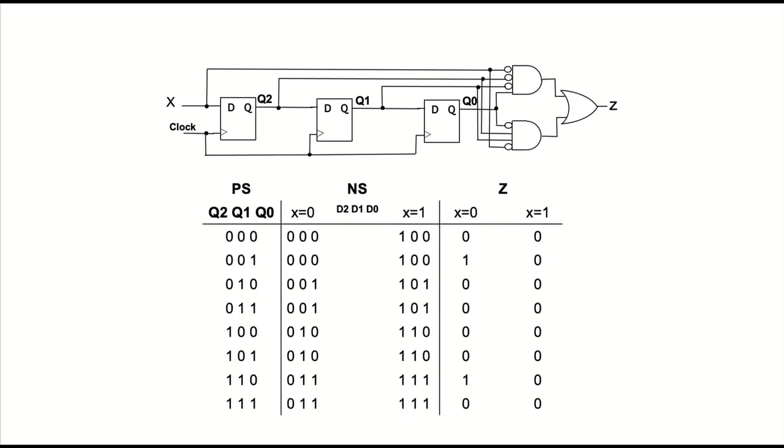We could draw a bubble diagram, but in this case, it's easy to make the table, because what we'll do is I'll call this one Q2, Q1, Q0. So when I put them in the table, they go left to right. And then this shift register, what's in the shift register is essentially my state. That's what it remembers about the past inputs.